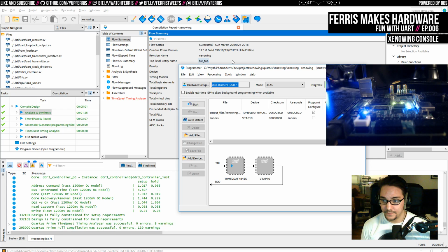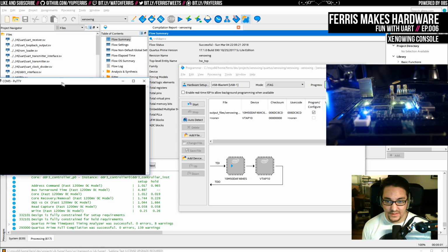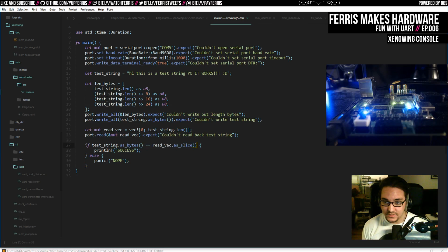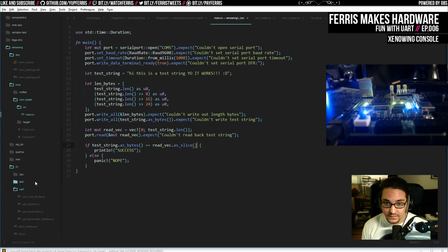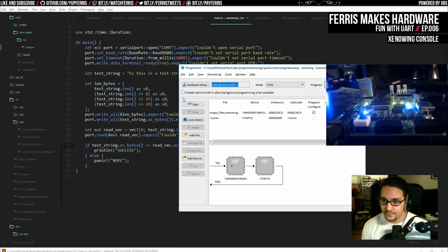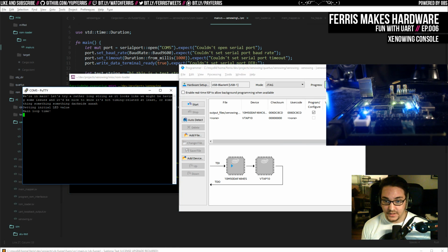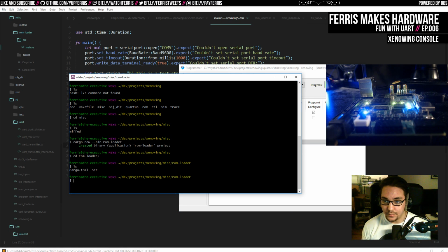So this finished. I am actually going to open up PuTTY really quick because I want to see if this works just like it did before. And that's COM5. Also, I think the name of that port might be off. I should, before I forget, I think, okay, no, never mind. COM5 should be fine there. PuTTY, and we'll run this. Looks like we're good. Now I need to close PuTTY because that's going to hold that COM port, otherwise we can't open it.